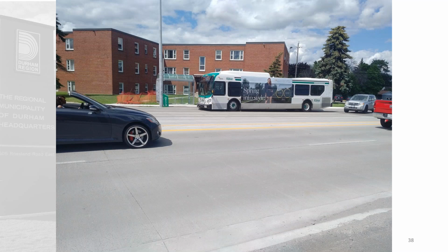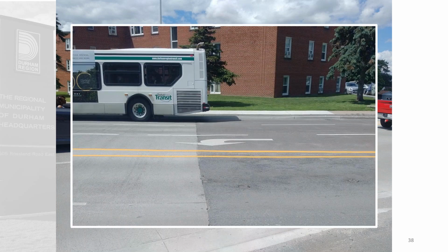Here's a picture of one of our buses stopped at a bus stop within the limits of the concrete paving. You can see here we designed the concrete to extend beyond where the bus stops. And we did that because we wanted the bus to be fully on the concrete and not bridging over the joint. So this asphalt to concrete transition, I showed you that detail before, where the concrete actually extends a couple meters under the asphalt, it continues beyond where you see the asphalt starting. But we didn't want the starting and stopping forces to bridge across that transition. And this puts all the forces directly on the concrete, which is, I think, better in the long run.